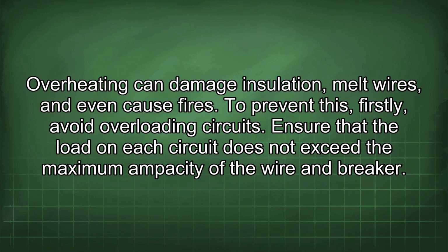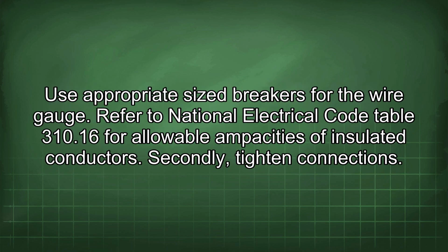To prevent this, firstly, avoid overloading circuits. Ensure that the load on each circuit does not exceed the maximum ampacity of the wire and breaker. Use appropriate size breakers for the wire gauge. Refer to National Electrical Code Table 310.16 for allowable ampacities of insulated conductors.